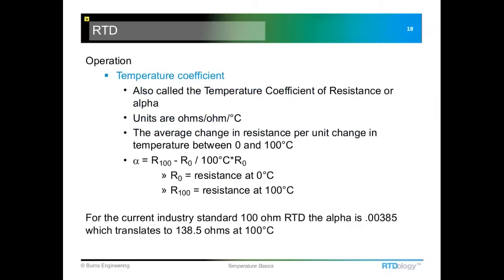But one of the easiest ways that I try to explain this is like a temperature probe RTD, or I should say PRT or PT100, that follows either one of the ASTM or the IEC standards. The temperature coefficient is 0.00385. So at 0 degrees C, all of these RTDs are going to read 100 ohms. And at 100 degrees C, it'll read 138.5 ohms. And that's kind of the easy way to look at the definition of that temperature coefficient.